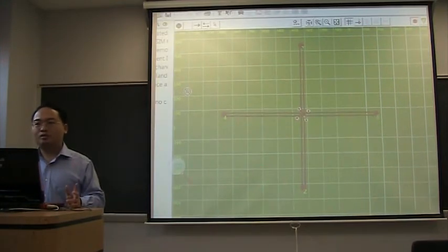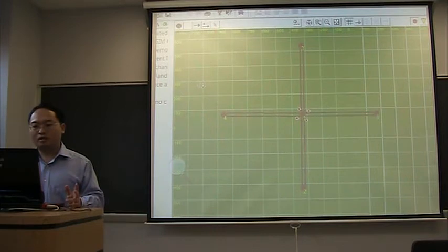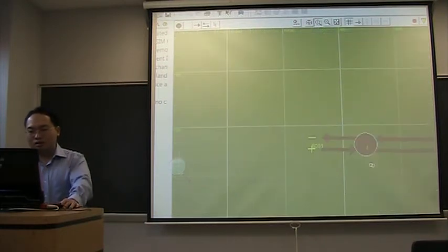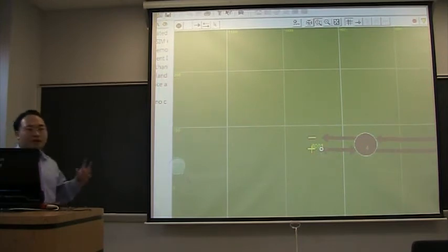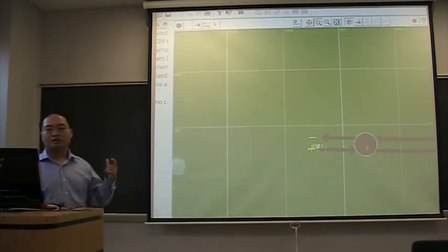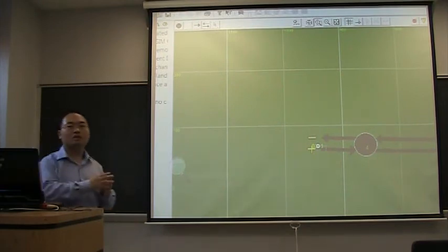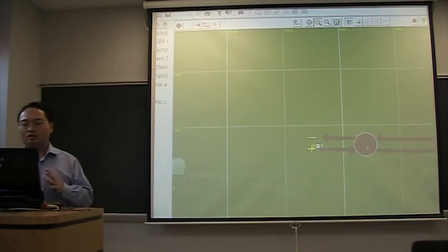The next step is to provide vehicle input or travel demand. In order to do that, we need external nodes. So watch carefully how I did it. I'll select this two-way link, and I select this node, and click somewhere else. And here, you will see another node which has a very high node number created. And this indicates an external node that we can use for providing the traffic demand.